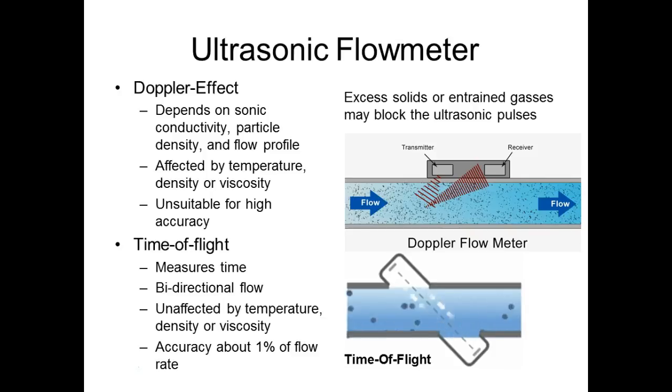Well, time of flight goes through. Yeah, but it's a radio wave... I'm sitting there thinking it's an ultrasonic wave. Yeah, it's an ultrasonic wave. Both of these are ultrasonic. These use high frequency right up in the ultrasonic range, send out a pulse, and then what? One of them looks for reflection, how it's skewed when it reflects, right? And the other one shoots through the fluid and then looks for it to come back.